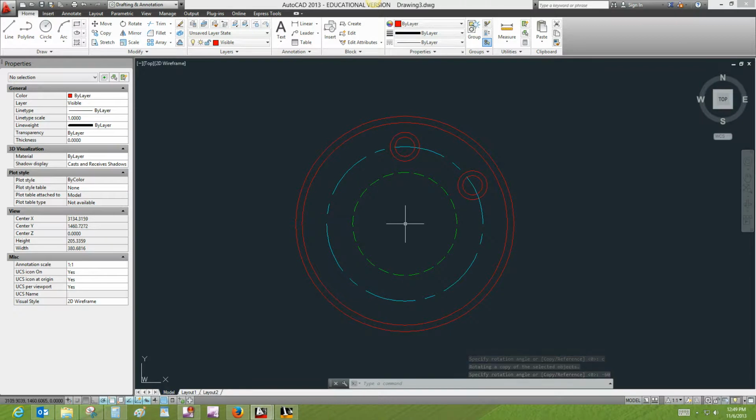Okay, so the 3 drilled holes, none of them are actually on any of the main axes. But that's not a problem. We can just use our polar tracking and then find out where the 30-degree angle is, which is showing up as 120 right now. Remember, it's measured from the horizontal.